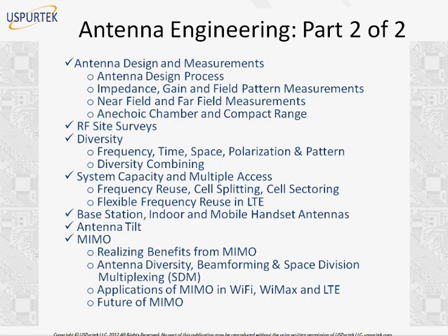And after that, we move on to how we can add to the wireless system capacity. If we want to increase the number of users served by a typical wireless system, a typical cell tower or a Wi-Fi LAN, what are the different techniques we can use to add to the system capacity? You might have heard of some of those techniques like frequency reuse, cell splitting, cell sectoring. Then we'll also talk about the advanced techniques used in LTE, the 4G LTE networks, of flexible frequency reuse.